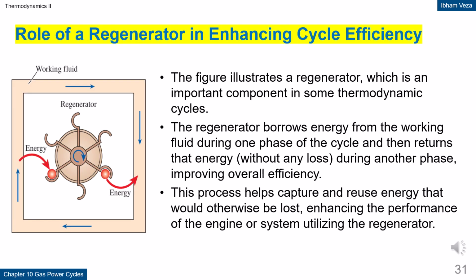A regenerator is a component that temporarily stores thermal energy from the working fluid. This heat is then returned to the fluid at another stage of the cycle without energy loss. In this way, the required heat input from external sources can be reduced. The result is an improvement in the overall thermal efficiency of the cycle.